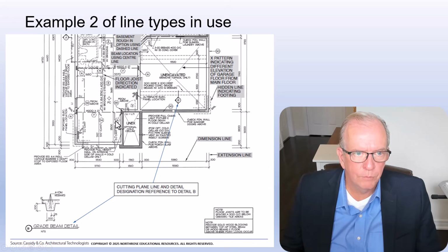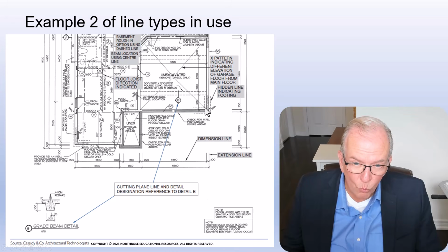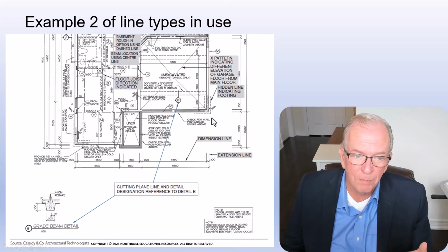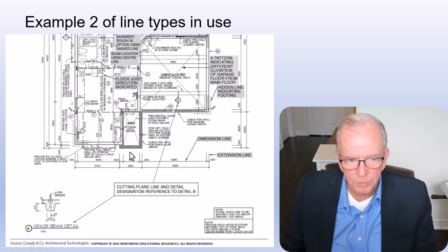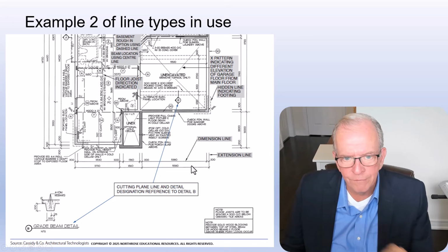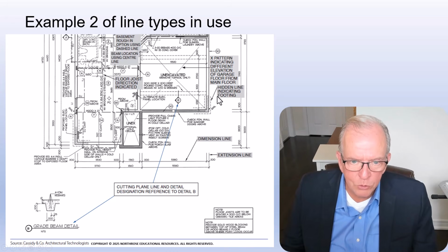We already talked about the floor joist and basically the rough-in aspects. Oh, and these are extension lines. That's the other thing: extension lines very often don't go right up to the building. I don't want to make them longer than I need to, but I like to stand it off from the actual building, or this designer likes to stand it off. But I find students very often, if I ask what the thickness of the wall is, keep looking here and don't expand their field of vision.